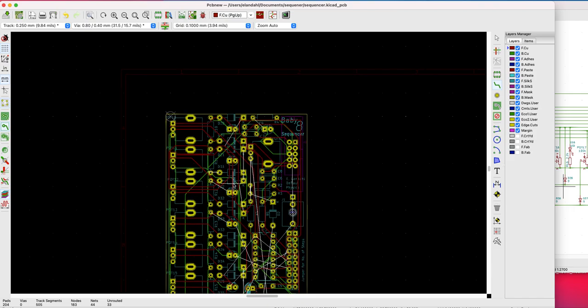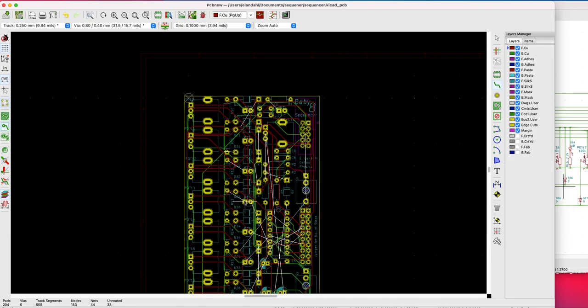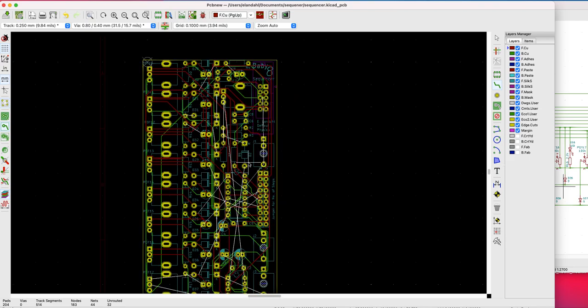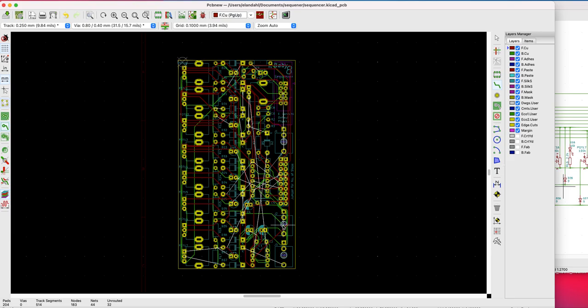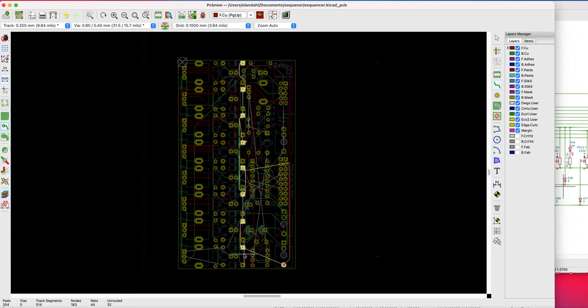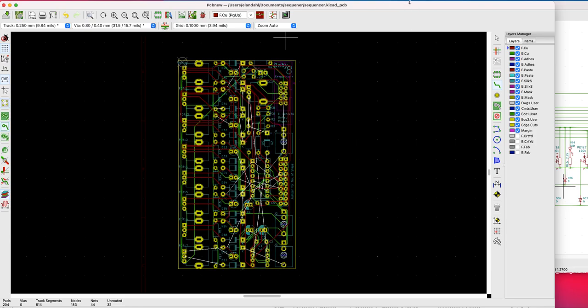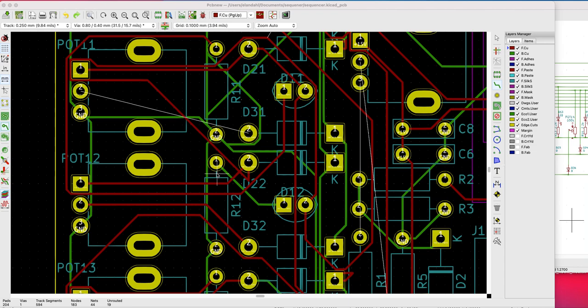And once this is done, we'll want to go back, clean up traces again, and see where we are. The idea is to keep the final desperation stage, which is adding vias or pass-throughs, to an absolute minimum. Actually, you'll be down to traces which you cannot complete.